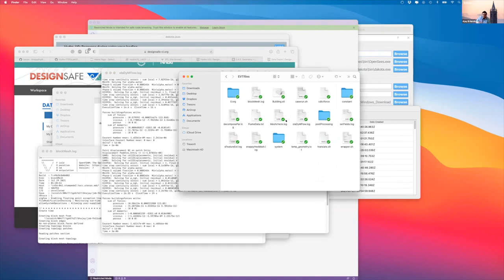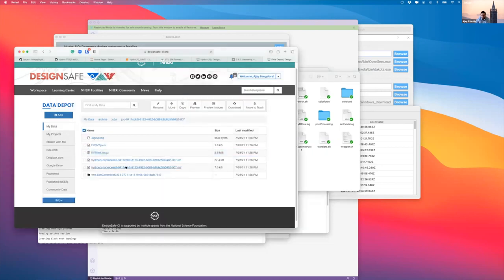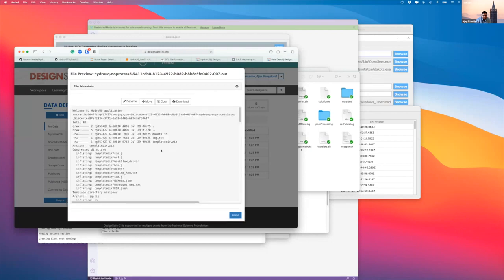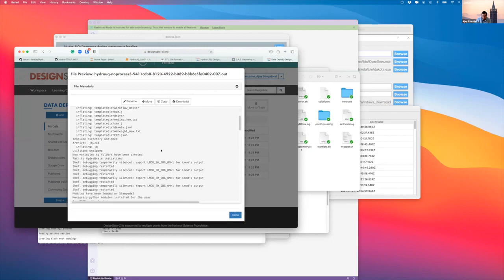So you can look through them, and if something is not working, you can see that this is where my job failed. If it fails elsewhere, then you probably also know. One other place to look for the bug, if something goes wrong and you get a failed message, is these two files, .out and .err. When you're trying to do CFD, most often you will get some cryptic messages, and these are files where you can look and try to find your error message. Now let's see what went wrong in there. If you open the out file, you'll see everything that is being done here.